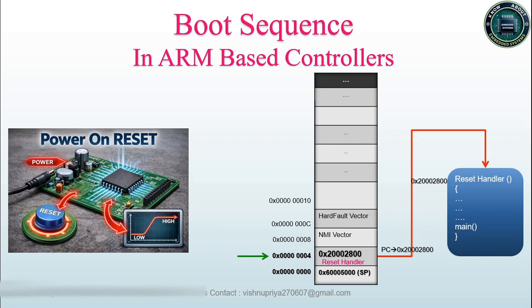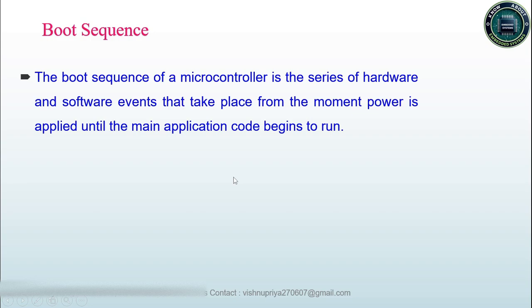Booting sequence in the ARM based microcontrollers. So first of all, guys, what do you mean by booting? The first question you may get in your mind is, what is called booting? Booting is nothing but the steps which occur from reset till the starting point of your main program.